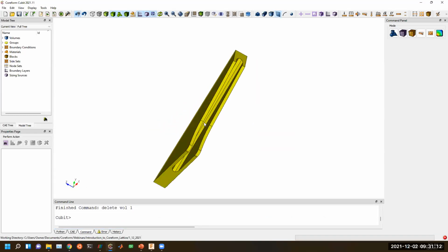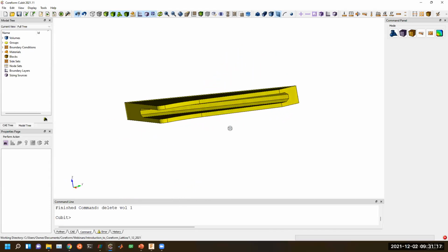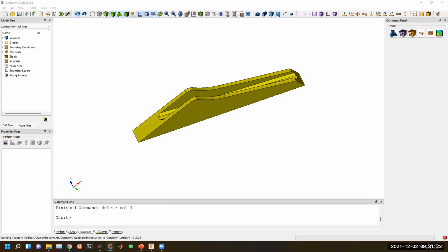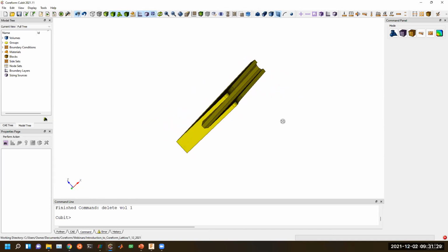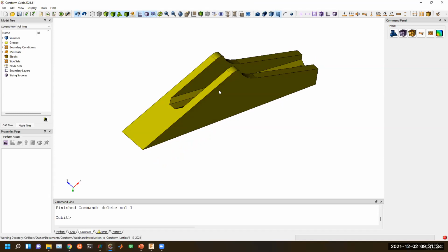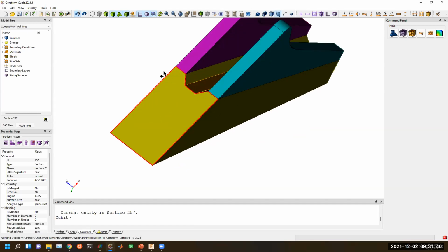Again, we start by working with our lattice structure region. This is a complex region we're going to fill with lattice structures. The first thing we're going to do is web cut this into hex-meshable sweepable regions. I'm going to first sweep these surfaces through to chop off these top two regions, and then I'm going to slice with this plane here to slice off these two nubs.